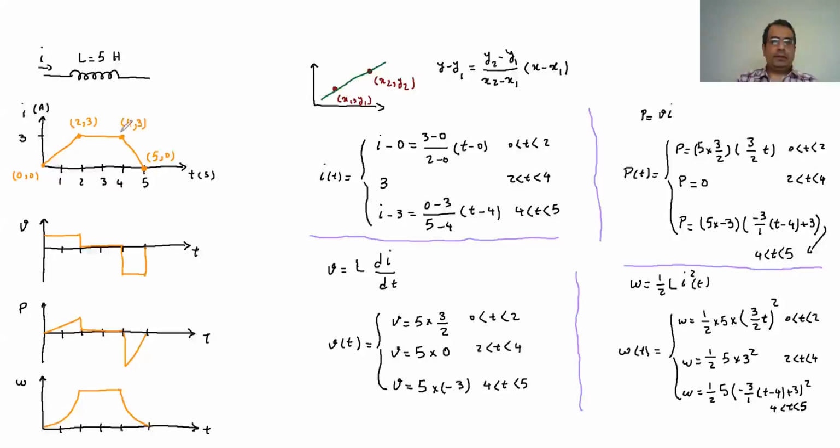And then when the current starts to drop, again, the inductor hates the change, so it starts to fight. How is it going to fight? As soon as the current starts to drop, it doesn't want it, so it starts to release its energy as a current into the system. So its voltage becomes negative. Basically, it changes its polarity in order to release the energy into the system.